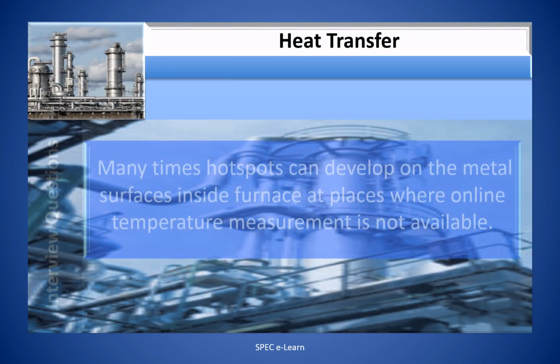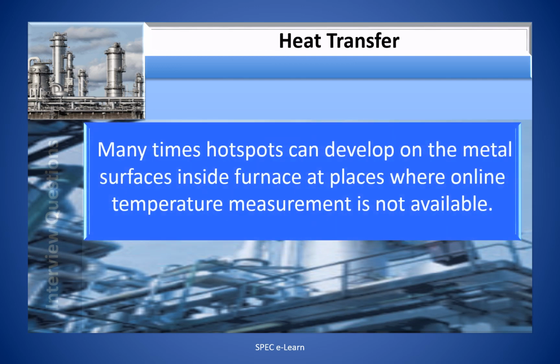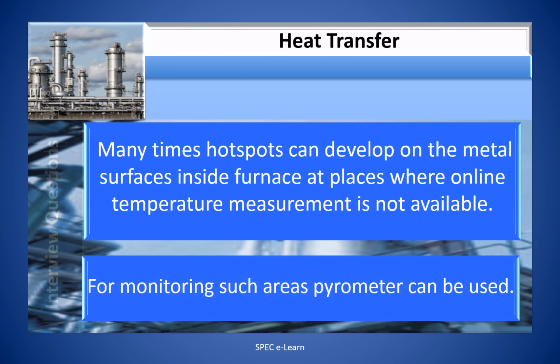Many times, hot spots can develop on the metal surfaces inside the furnace at places where online temperature measurement is not available. For monitoring such areas, a pyrometer can be used.